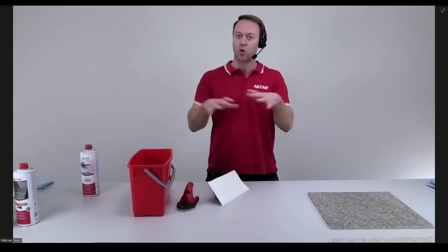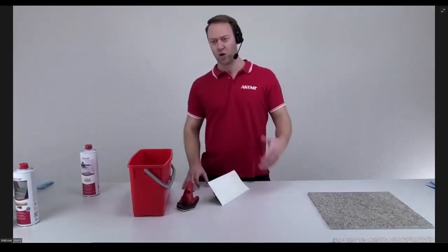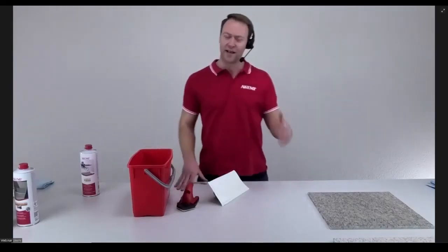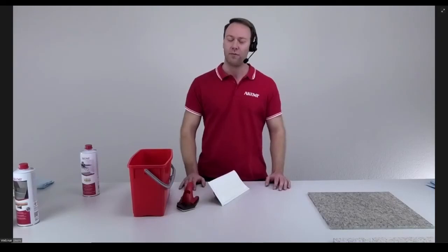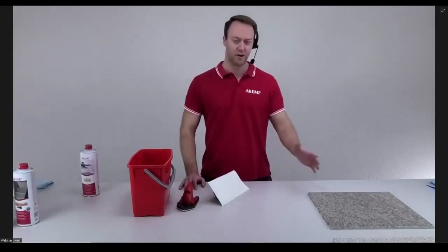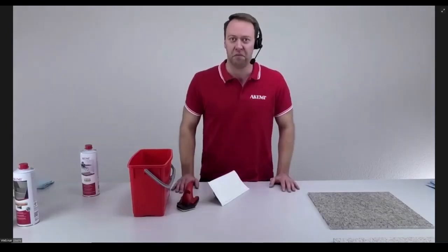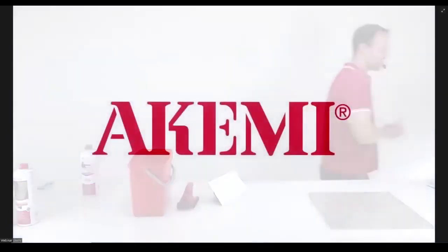So on marble and limestone, especially when it comes to outdoor applications, I would recommend a treatment maybe every 1 or 2 years. But on a granite, on a hard stone, many years, no issue. Okay, so let's move on to the next topic.